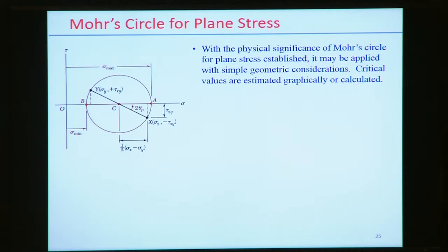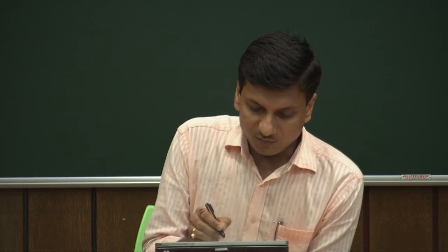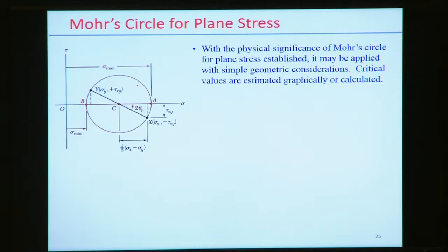So this is the typical picture of the Mohr circle. How can we draw the Mohr circle? First define the axis system and origin O. Assume that along the x-axis the normal stress is represented, and along the y-axis the shear stress is represented.